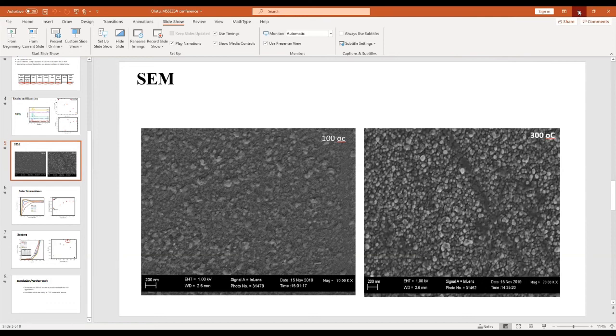Then for the presenters, Lillian and Ibrahim, for Ibrahim, this is my question. What were you aiming at when you are adding antimony to titanium oxide? Because from what I can see, the band gap of titanium oxide, if you added antimony, reduced to around 2.8 or something like that, which means the absorbance of that layer will go even into the visible region.